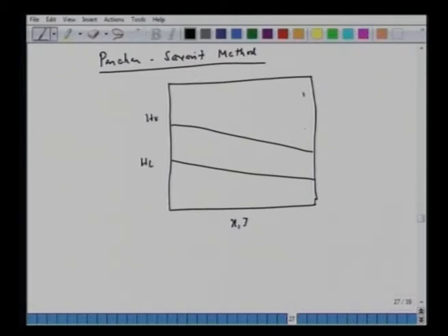Then we said that corresponding to this xt, say in case of total reflux, we mark this point del xt, which corresponds to the coordinate q dash, which is qc, the condenser load, plus D ht. So a hypothetical stream leaving the system with the condenser load and the top product, divided by D.